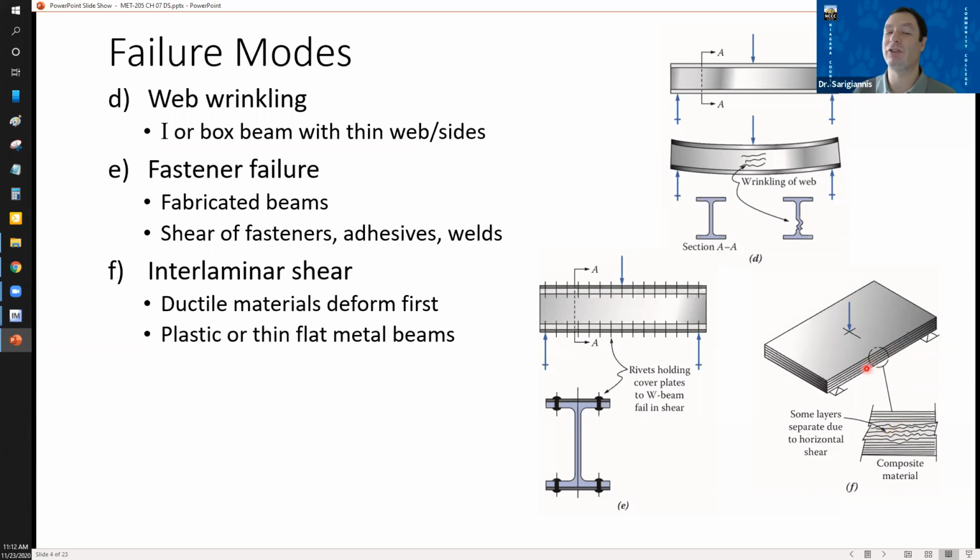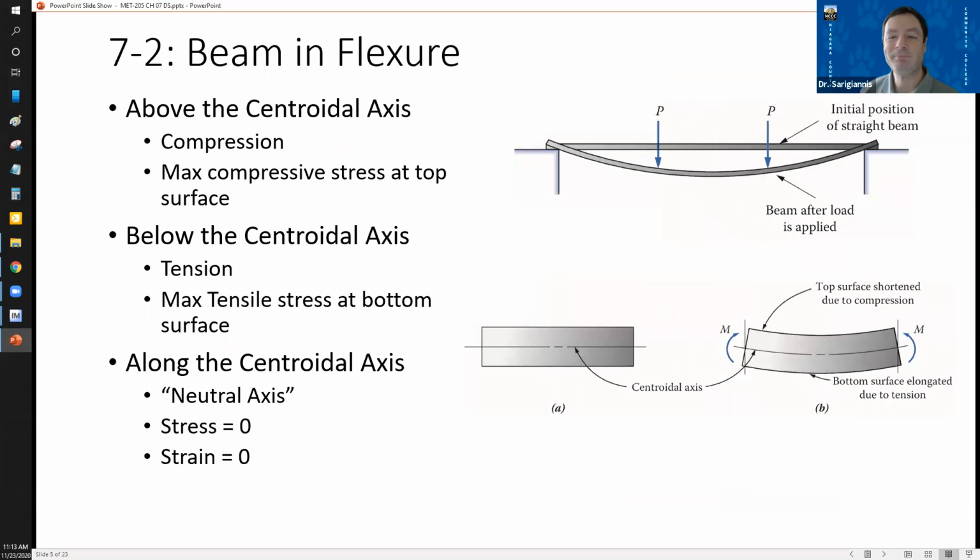I've definitely seen this with certain ceramics. I used to work in a place that made boron nitride, which is this really cool laminar ceramic. And the adhesion between the layers is weaker than the layer itself, right? So if you bent it too much, it would start delaminating. So you can get this with any type of laminate structure or composite structure, plastics, right? Wood, thin metal composites.